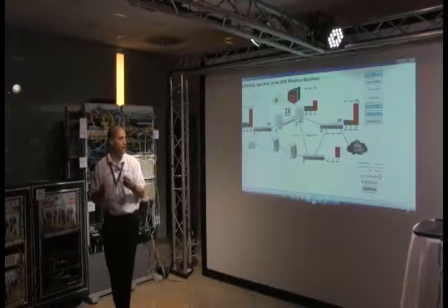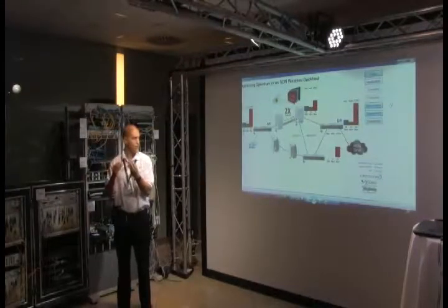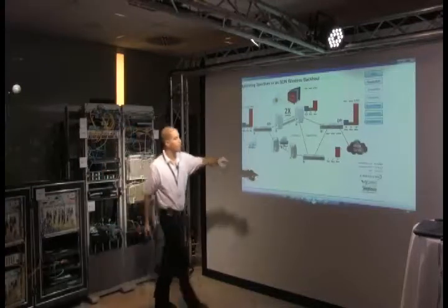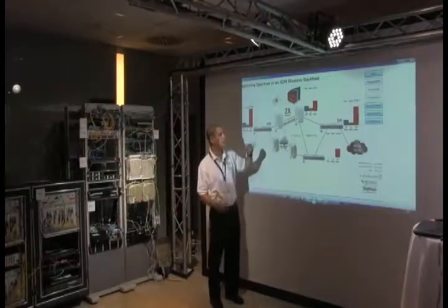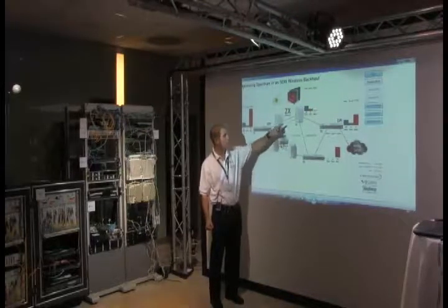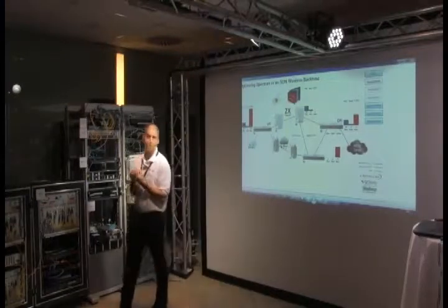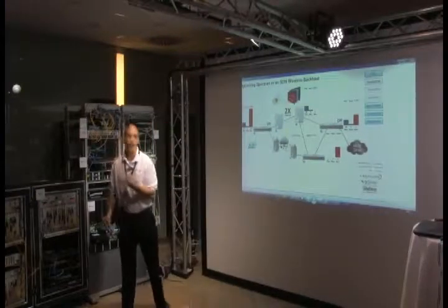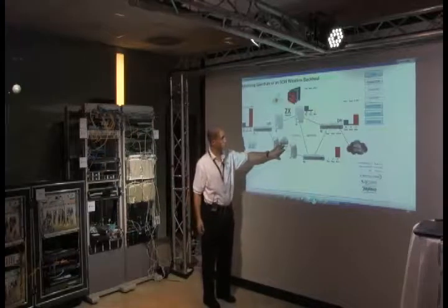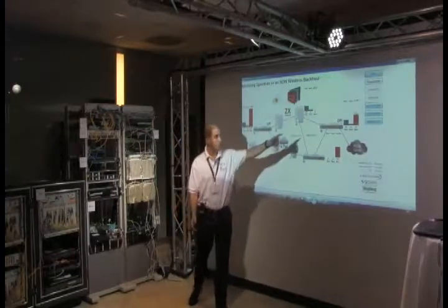But again, the trick is not that I doubled my capacity. The trick is that now I'm monitoring, this is something dynamic. So if I have a rain condition, okay, and now suddenly I have this condition of one microwave link interfering with the other one, okay, the application is going to gray out the extra link, okay, basically turn it off, only for the duration of time that I still have this rain condition, okay, and then I go back to my previous case where only half of the capacity is going through.